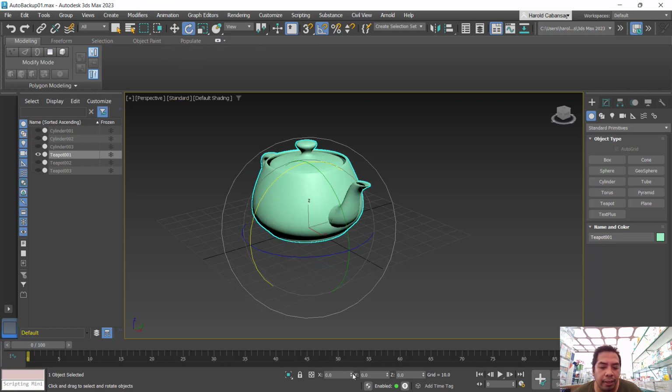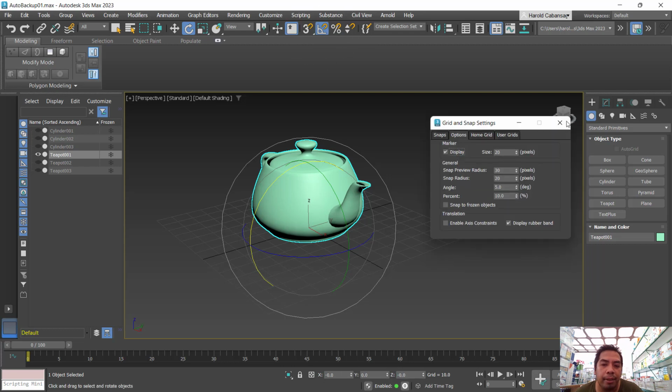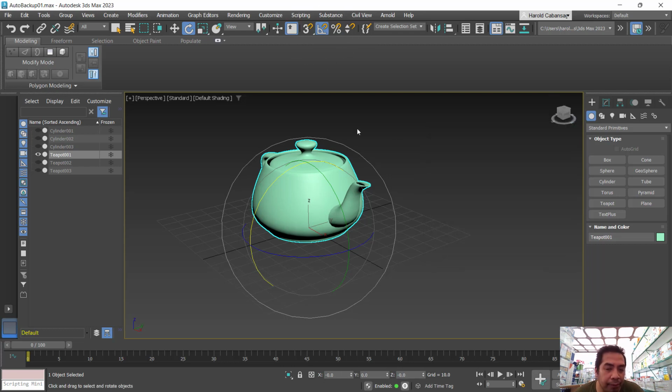Okay, so just reviewing, the rotate tool can also be accessed or have tool partners such as this, the degrees and angles settings, and also the angle snap. Now, if you are not going to be using the angle snap, you turn it off. If you are not going to be using the move snaps, you also turn it off because sometimes they work in conflict with each other.